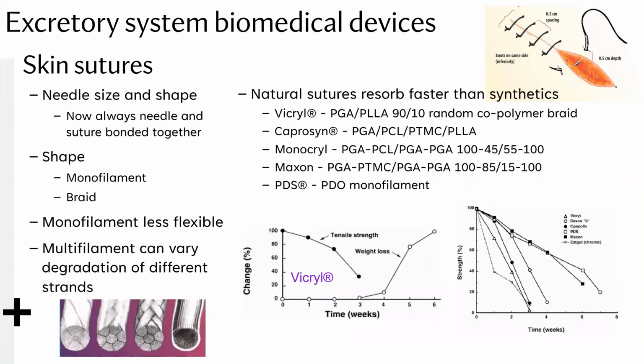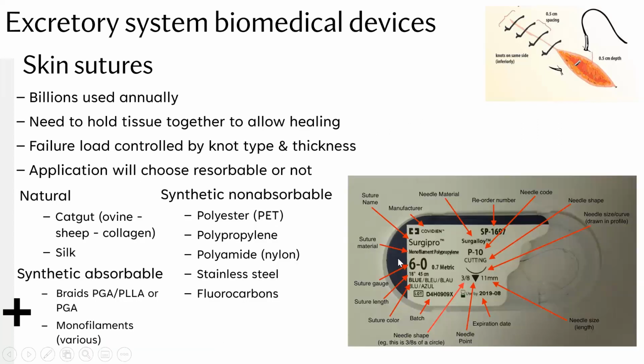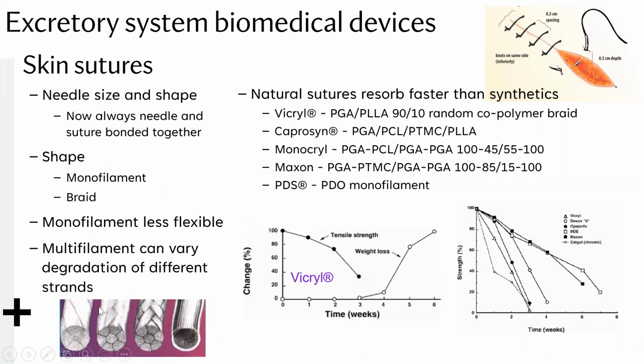And in terms of their geometry a little bit more, as you saw, the previous one was showing in the packaging monofilament polypropylene, and what that means is, monofilament versus multifilament. Multifilament is when you've got this braided structure, where you've got an entangled, intertwined configuration of multiple strands into one single thread. And in the other case, you've got a monofilament, which is a single material. You don't see it here. It's just that single strand that you've got.